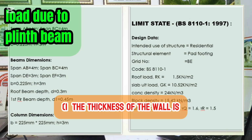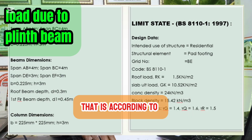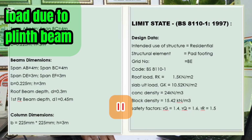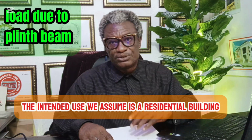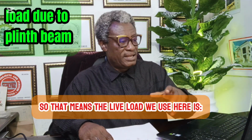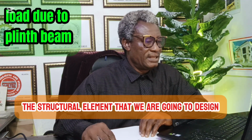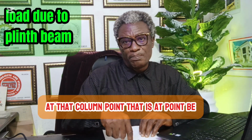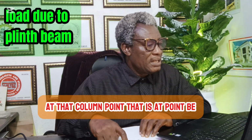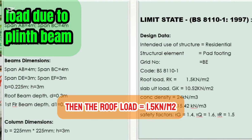One, the thickness of the wall is 225 millimeters. We're using the limit state design, that is according to BS 8110 part 1 of 1997. Then the building's intended use, we assume is a residential building. So that means the live load we use here is 1.5 kilonewton per meter squared. Then the structural element that we are going to design is the pad footing at that column point, that is at point B.